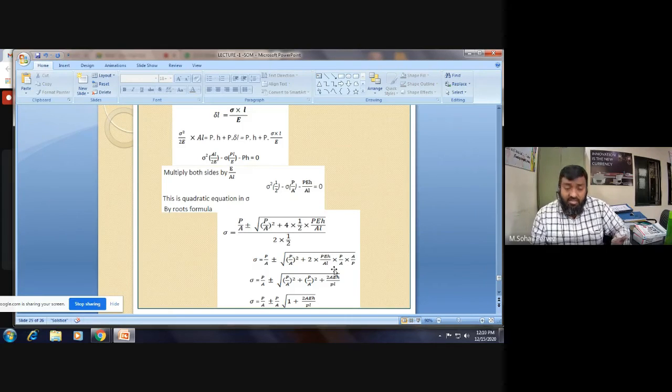You might have studied that example in mechanics of materials, on strain energy, where it is asked to compare or calculate the stresses. I must tell you that if the same load is applied gradually, the stress would be 4.5 megapascal. If the same load is applied suddenly, then the magnitude of that stress would be 9 megapascal. You might have solved that numerical. And the third case, impact. At some height of 50 mm, the same mass is dropped. In that case, the stress produced in the rod, not in the collar, was somewhere around 213 megapascal. See the difference: 4.5 megapascal gradual, 9 megapascal sudden, and over 200 megapascal for impact.